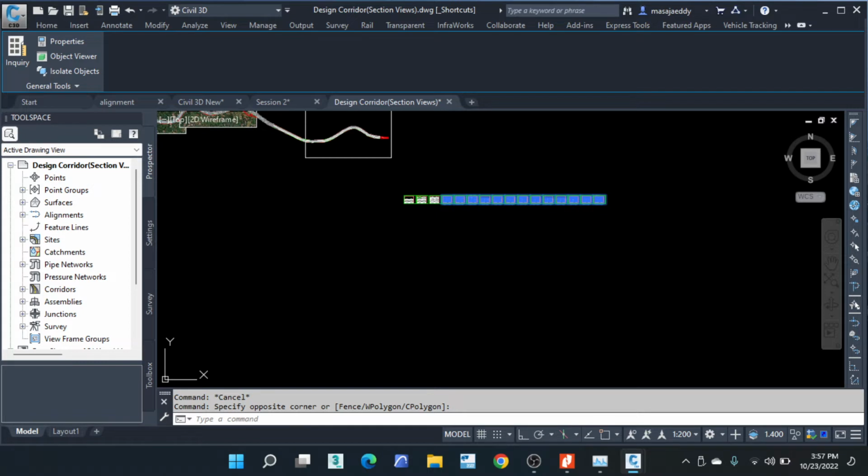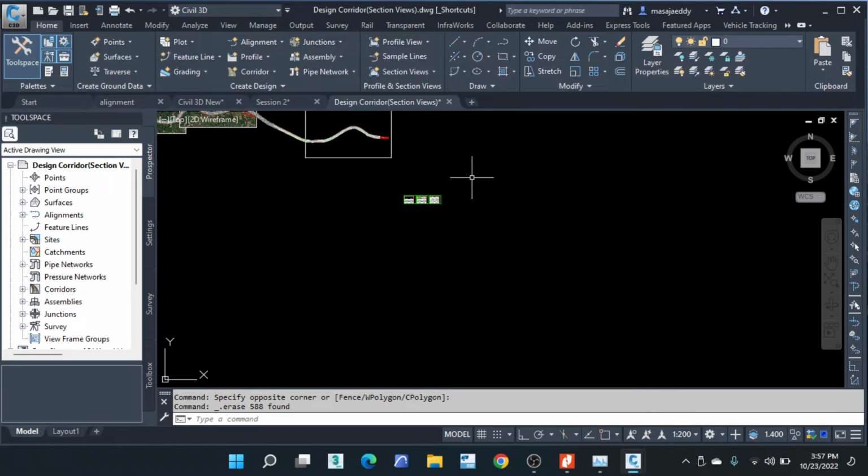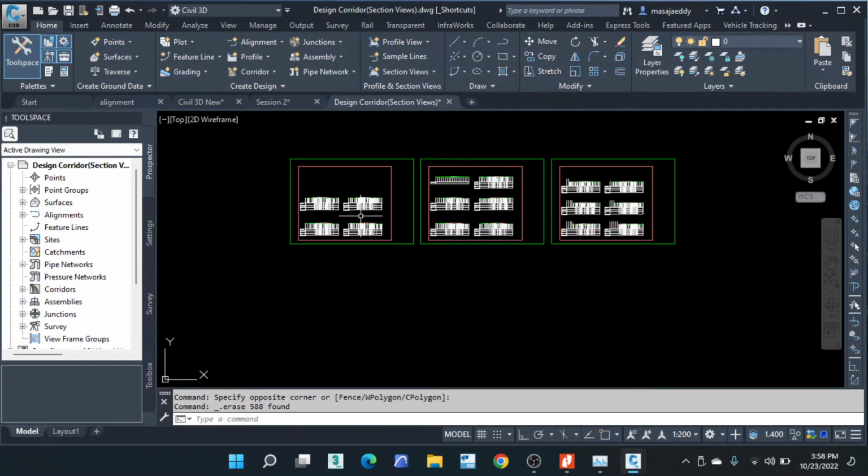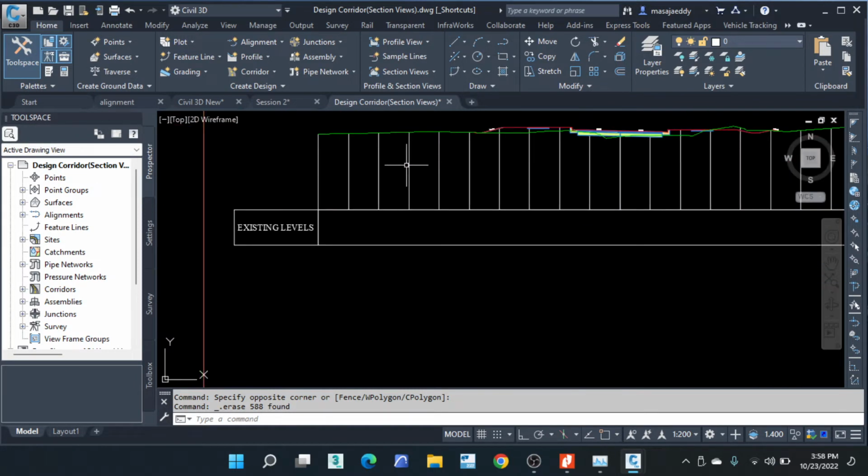Yeah. So after you've done that, you're going to save that section view, right? That section view property. Now, as that style is saved, and also you have saved your band set, you can delete all the sections, then you reproduce the sections once and for all with the edited section view styles. Okay? So sometimes some people first produce only one section view. You edit that to completion, then you go back and create all of them at once.